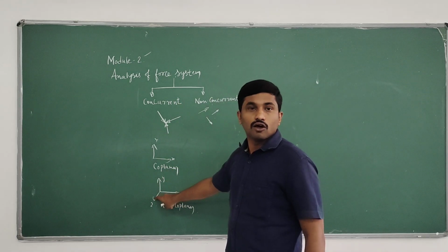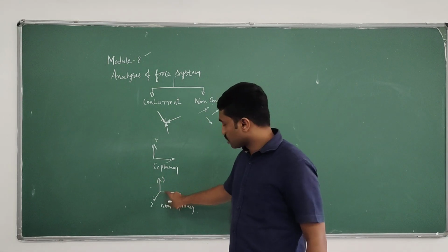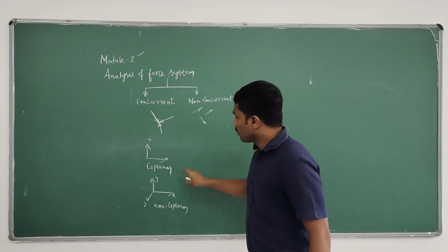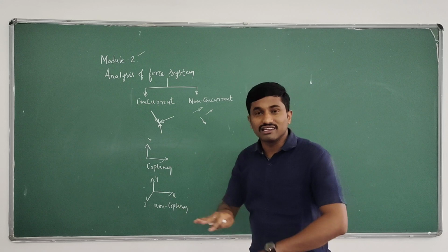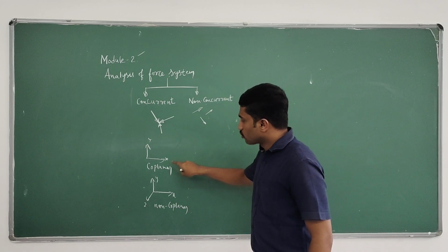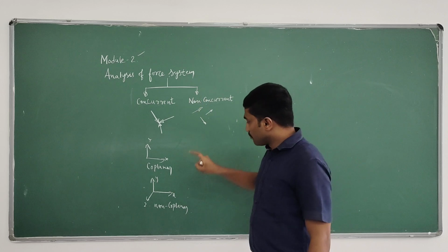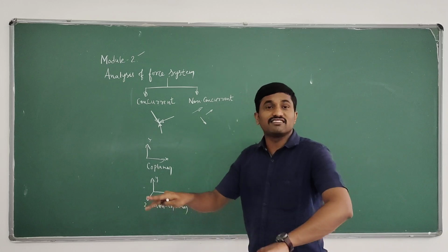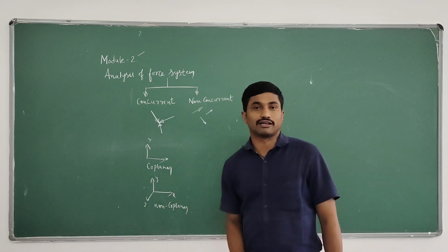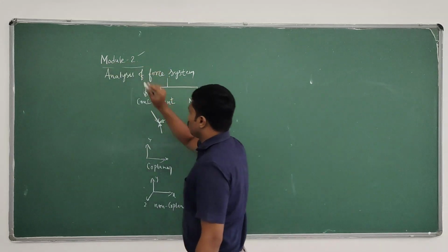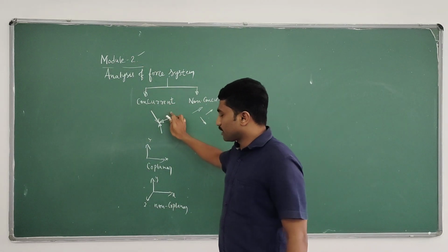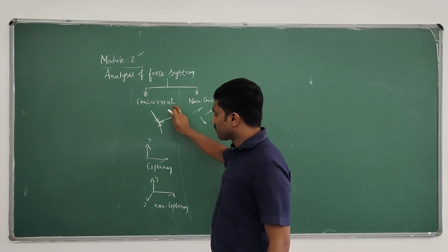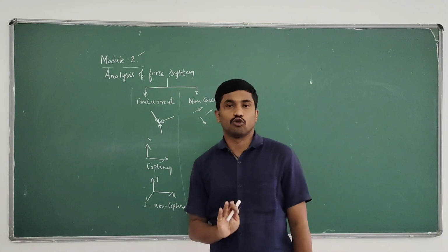In different planes, all forces meeting at a single point is non-coplanar concurrent. Similarly, in a single plane, forces that never meet at a single point are coplanar non-concurrent, and in more than one plane, non-coplanar non-concurrent. But in module number 2, we have analysis of coplanar concurrent and non-coplanar concurrent forces.